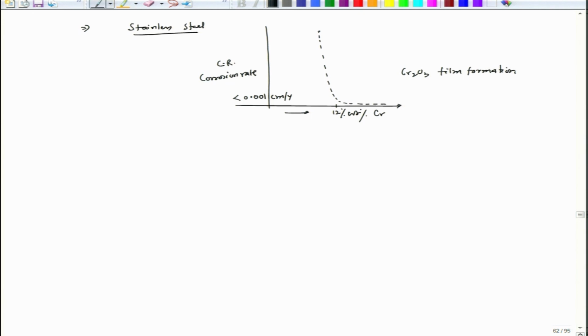In case of aluminum, it is Al2O3 that forms and which passivates aluminum. Now, an interesting part is aluminum is also considered a metal used as a sacrificial anode. As we noticed in the discussion when we talked about sacrificial anode, the anode material should dissolve spontaneously, so that it provides required electrons for the cathodic reaction on the cathodic surface, which is the iron, and that is how the iron is protected from corrosion.